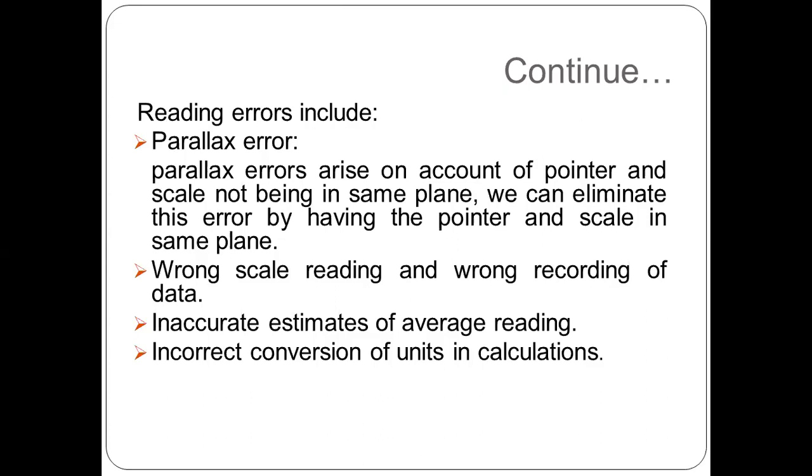These both are not in the same plane. There is a difference of angle. Okay, it means you are not only going to match this line, but you also have to match the plane of the particular line. Suppose you are measuring some part, explained with the help of a y plane measuring device. In that case, that is a parallax error. So in order to measure the length in your x plane, you have to put your measuring device in the x plane also. By this you can find out the parallax error.